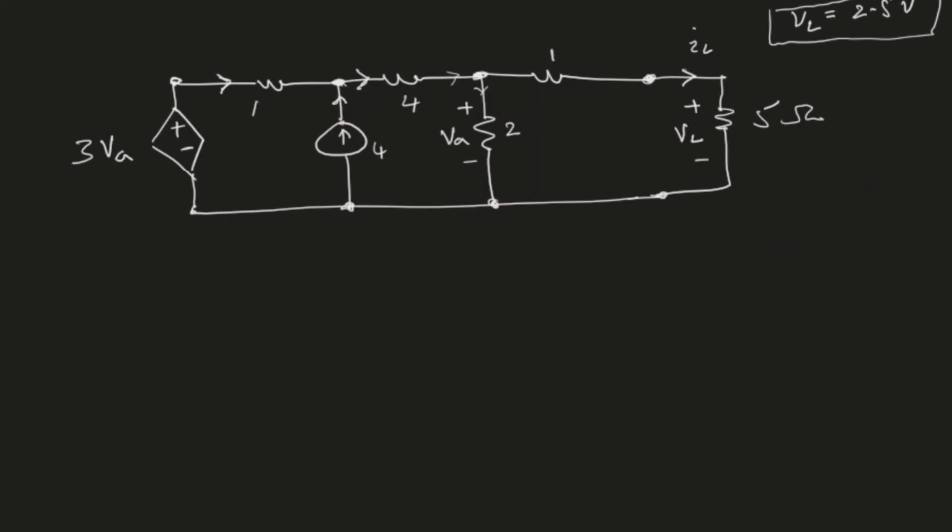So if I'm solving in my original circuit this time, let's use nodal analysis. I'm going to say that this is my reference node where the voltage is 0. I have one node V1 over here, and now I have a second node V2 because now we have a current that flows in this branch because it's not open anymore. So I have two nodes, which will give me two equations, and then we will find the two voltages V1 and V2.